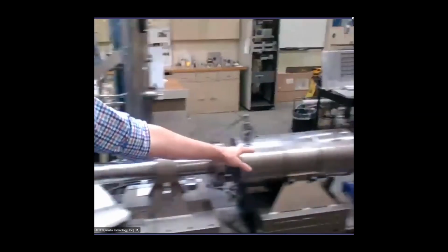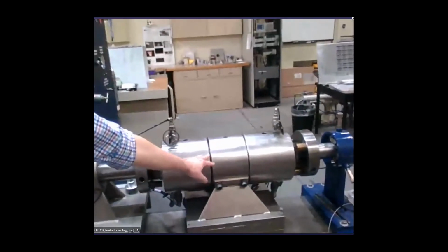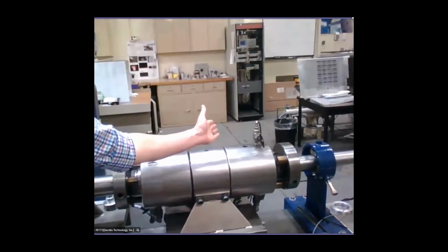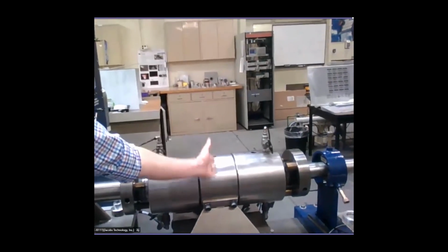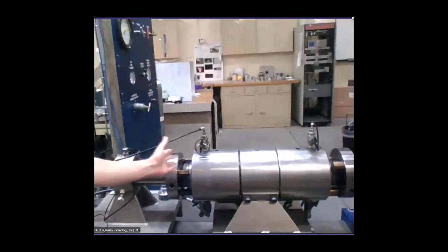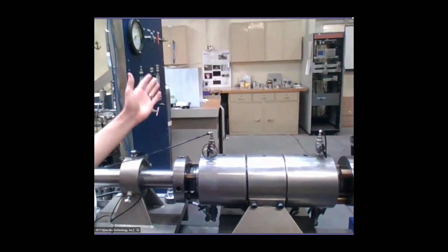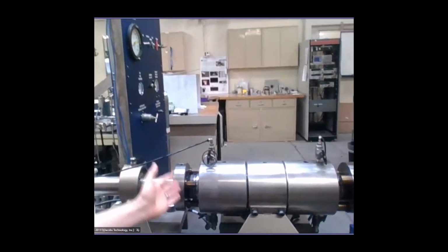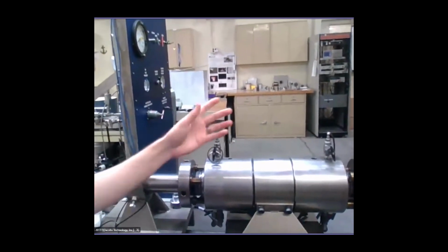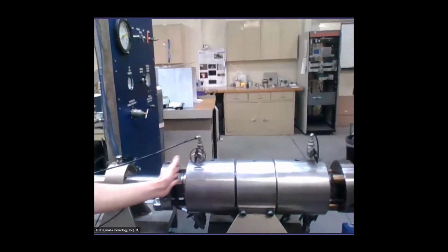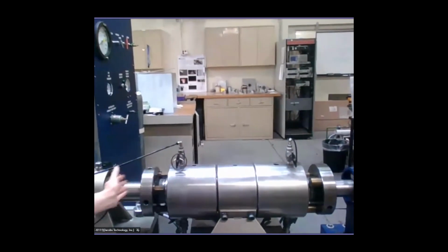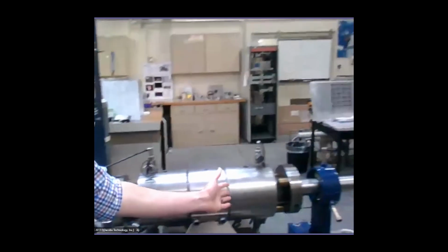hydrogen, because right here is what we call the high pressure coupling. And this is where we have a burst disc. This is a piece of steel that holds back all that hydrogen pressure until a known, it's calibrated. I should show you one of these. When we reach a known pressure, that disc bursts, and then all of that hydrogen is released from this side.